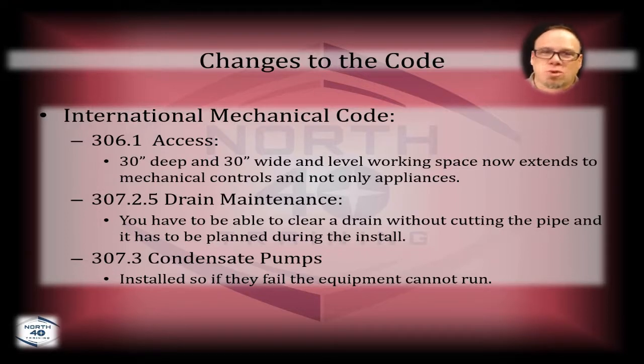But when you get up into 3/4, 3/4 likes to maintain its curled up status. So even when you're running across the floor, it does weird bowing things, and it gets all crusty a little bit quicker, and it's not nearly as cheap as a 5/8. So a lot of people use the 3/4 PVC because it's easier to run and they feel that it looks a little bit nicer. In my opinion, use what you guys use. Just make sure that you're complying with code. So 3/4 internal diameter is code, and you have to have the secondary drain hooked up.